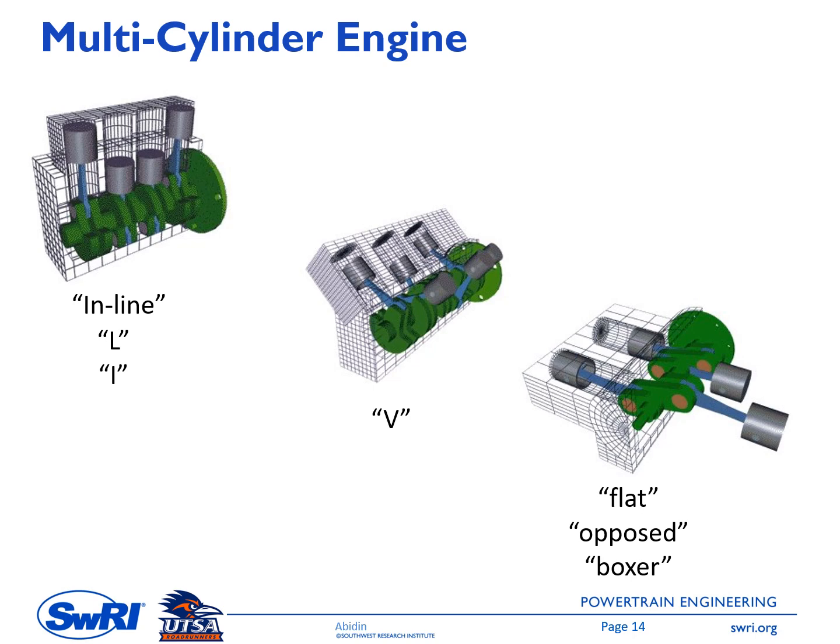And then the next one here is a schematic of a flat, or sometimes also called opposed, or a boxer engine. One of the car engines that uses this boxer is Subaru. Subaru uses this boxer cylinder configuration. You can see in here it is a 4-cylinder boxer engine, and then this is the crankshaft, and this is the cylinder head. So you'll have a cylinder head somewhere here.